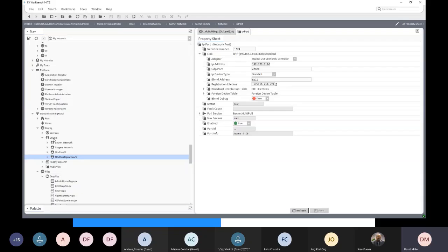So a 25 device license will cover you. 20 devices for the M-bus meters, plus 1 device for the Daikin BACnet gateway, and 25 devices is what, thousands of points. So yeah, away you go. Does that make sense?